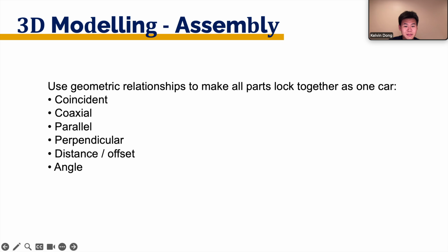Okay, now let's talk about assemblies. This is about how to mate parts together. We are building towards a full car. In CAD, an assembly is just a group of parts locked to each other using relationships, just like what's listed on the slide. And here's what that means for us. Wheels should be aligned coaxially on their axle center line. Axles should sit at the right height plane relative to the track reference. Things like that. When you do this right, the assembly behaves like the real car. When you don't, you end up forcing parts together in the shop because CAD said it fits, but CAD was lying.